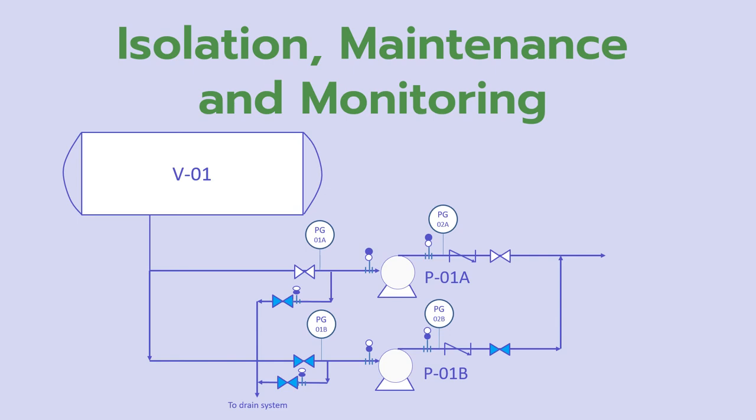This is also applied on the pump strainer at the suction. The job of the strainer is to make sure that no significant solids will enter the pump, especially during startup when the pipes may not be clean. So if the strainer was plugged, this means more pressure drop. During startup, operators need to monitor the pressure drop in the strainer, and when it reaches a certain value, there will be a need to dismantle it and clean it. So we shall need here a pressure differential gauge around the strainer. These are the basic instruments added to monitor the pump performance.